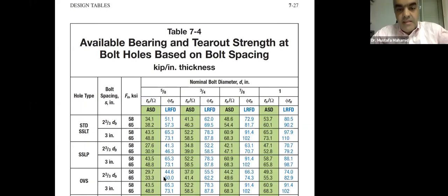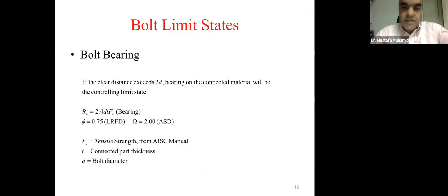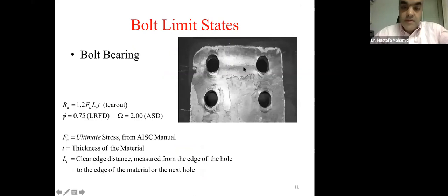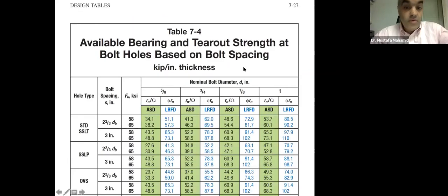Okay. Again, the values here are given for a small rn, that's per 1 bolt. So if we have, for example, 2 bolts, like the figure here for the tear out case, then we multiply the capacity by 2. If we have more than that, 3, 4, we multiply it by that number.